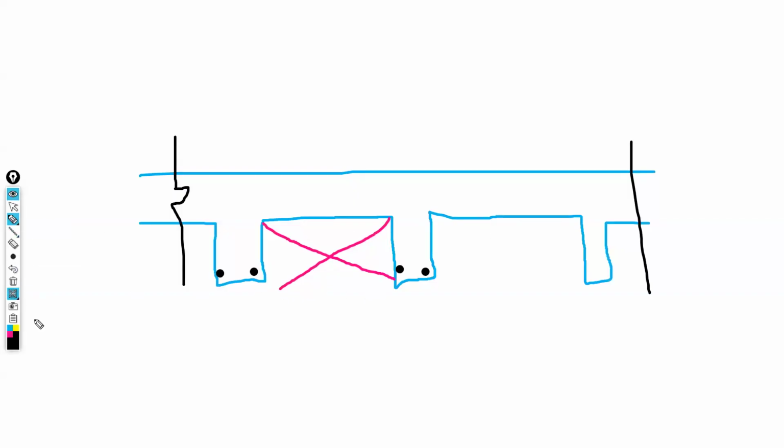Now, we have some parameters to define. One is the overall depth of the slab. It is going to be taken from this point up to the top. So this is the edge. This is H. What depth of the slab have we been using? 200. So I'll have 200 here.